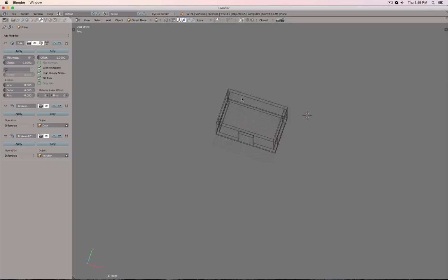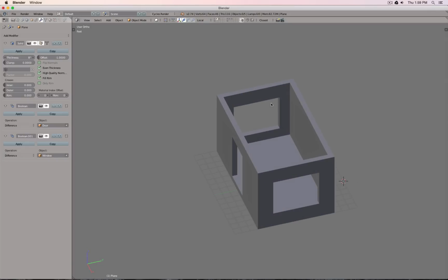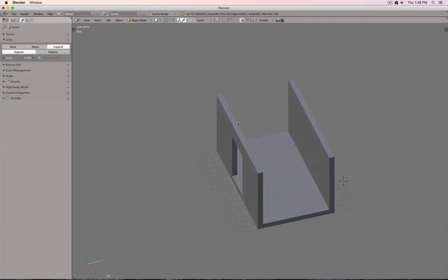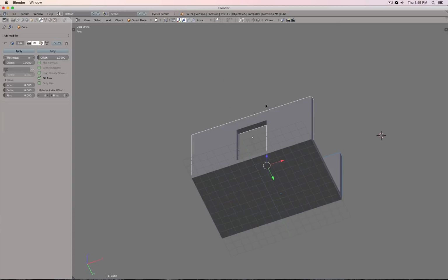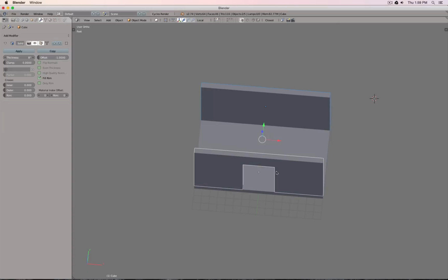And let's go to this layer and you will see how you have to prepare your different walls and the width, so later when we laser cut everything, you can just stack it back together and it will all fit. So you see that here I have my front and my back wall and they are as wide as my base plate.